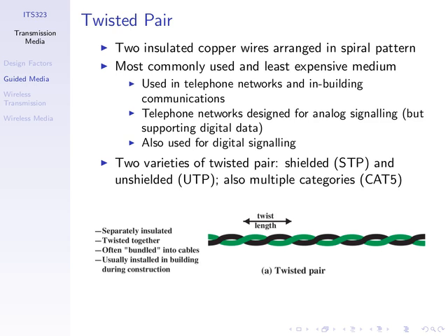the design of the systems. One factor is that we know that the signal gets weaker, and it depends upon the transmission media how much the signal gets weaker. So most technologies would have some limited length. You cannot use a cable longer than 100 meters, is the typical length. Because of the design of the cable, there is always some interference. If you're greater than 100 meters, the amount of noise that comes onto the cable will be too large,